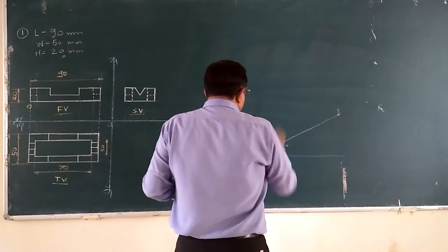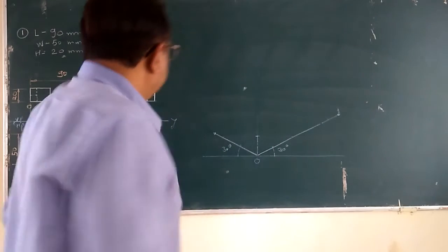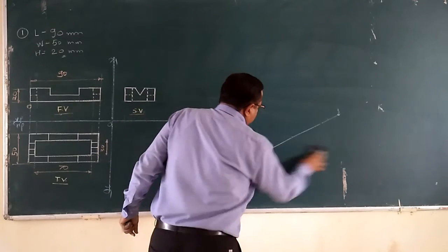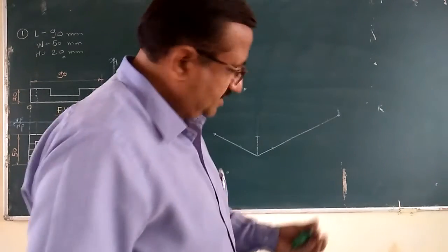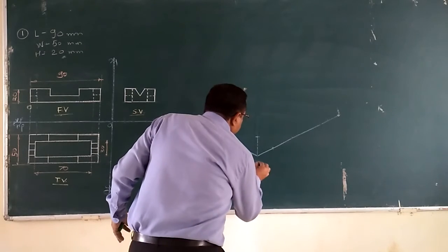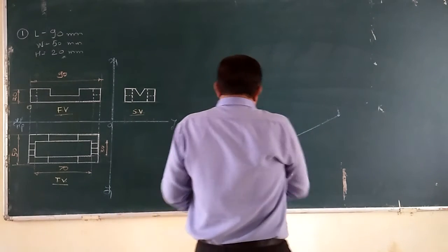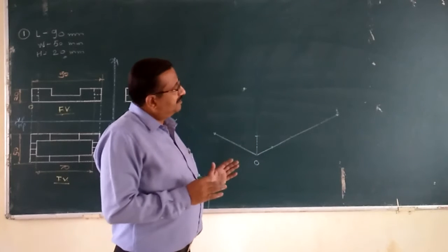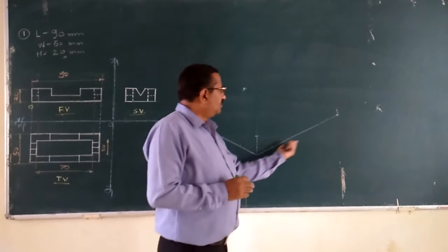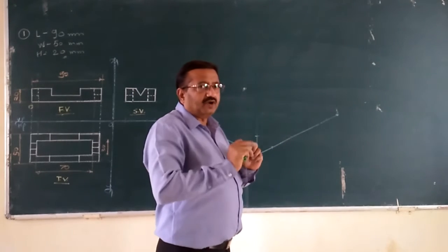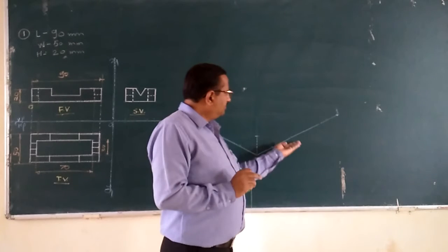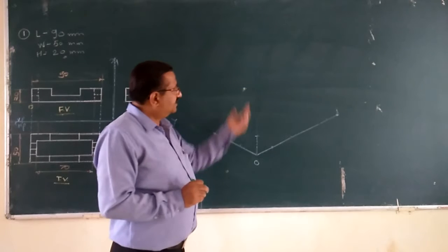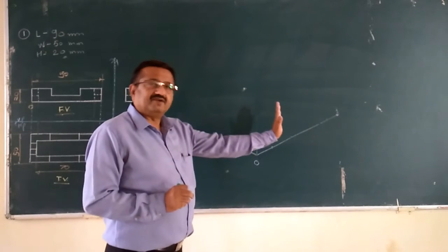With this L, W and H, we have to finish the 3D box. Now you can retain or erase these lines. These are not essential. Now what do I have to do? With the use of your friend, the roll and draw, that instrument you have to use now. Make it roll by coinciding the edge of the roll and draw with this line to get parallel right 30 lines. With this edge, get parallel left 30 lines, right 30 lines, left 30 lines and vertical lines.